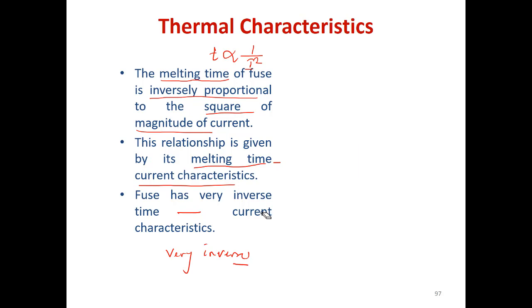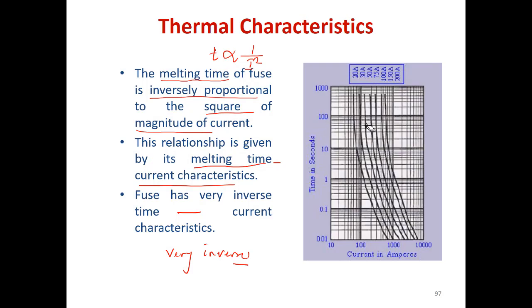We can see the characteristic here. It is really very inverse. As the current increases, the time required to melt is very small, in terms of milliseconds.